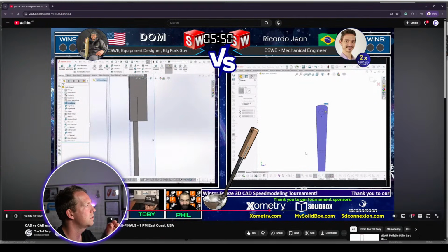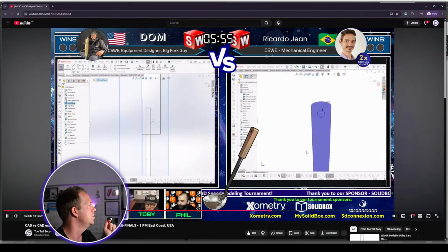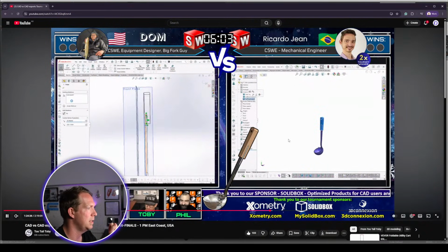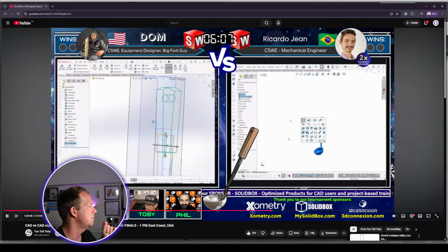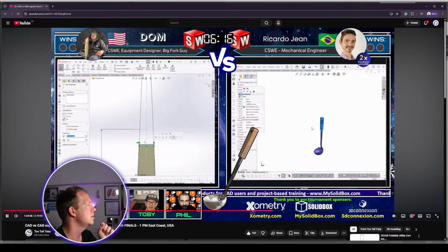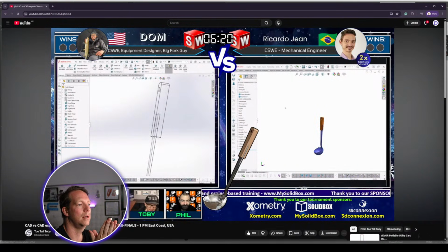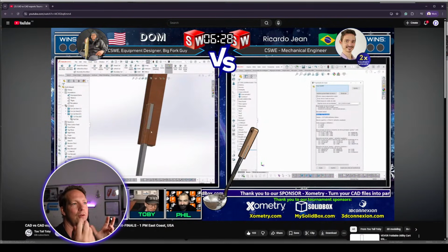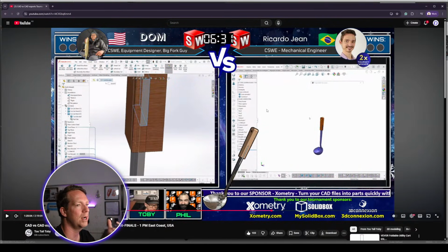You know, they're doing it slightly differently with extrudes both ways. Aaron C in the chat here with a great recommendation after the guys had passed this, that this is for an indent tool. This is the perfect place to use it. The indent tool lets you take one body and use that to subtract material from another without removing the body. So it's different from the combine tool.